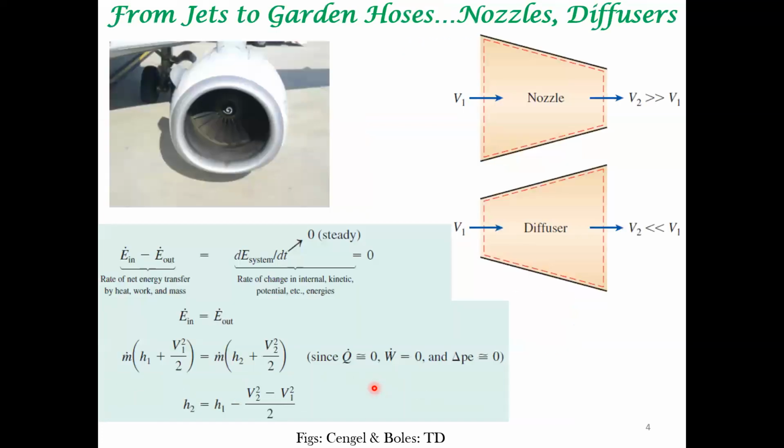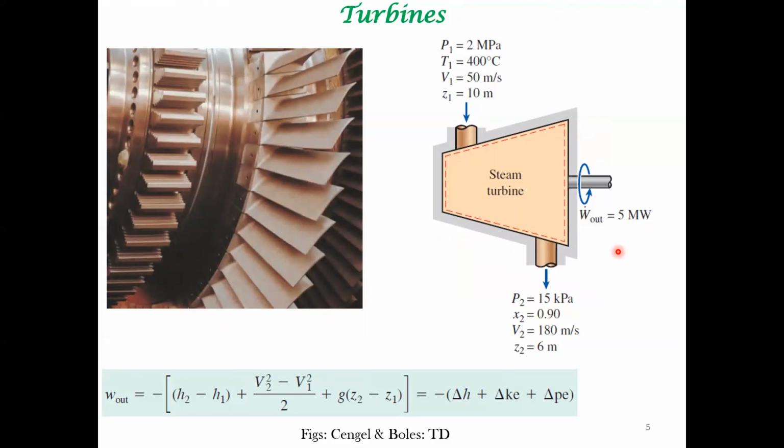If you see, for example, in the previous case, there was a diffuser which served a particular role, right? Here, what did we say? The velocity is less, the pressure is high, right? So the diffuser is also integrated into the system, and it serves a certain purpose. We are not going to analyze the design of a turbine, why the turbine is designed in this particular manner. All we are going to do is bookkeep these terms involving enthalpy changes, kinetic energy changes, and potential energy changes.